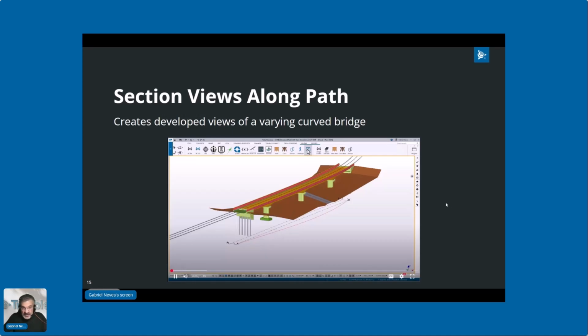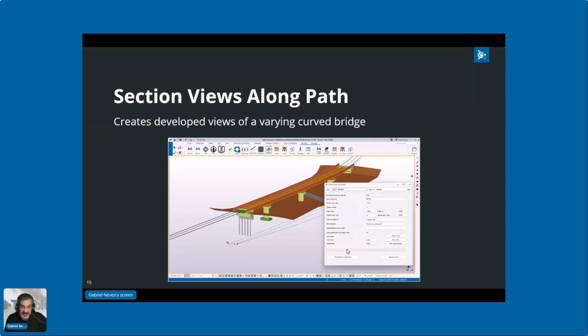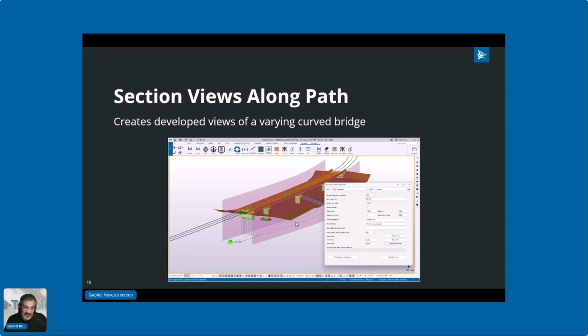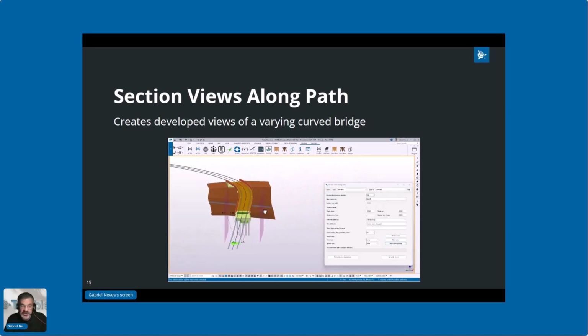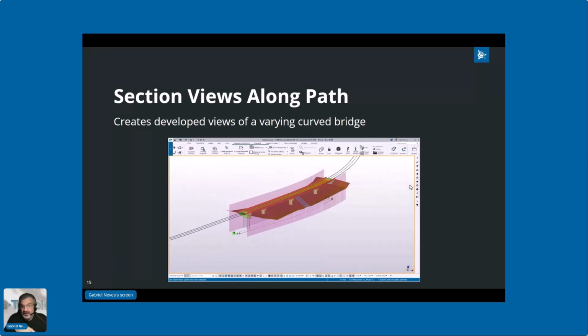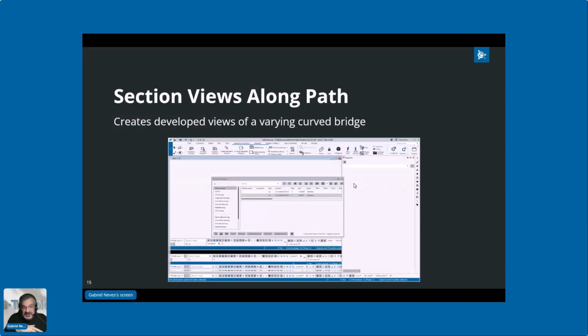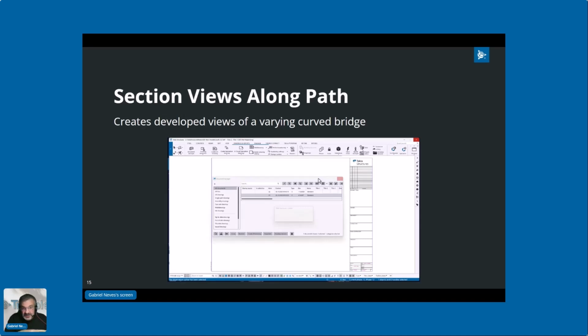So now when we get into the extension, we have already the short line. As I said, we're going to use that. We could pick the 3D, but I'm going to pick the 2D. So now I'm going to look north, and then here just to see the crop view. Eventually I say generate views. So it's a GA with just one plan. And now I'm going to have maybe 80 or something like that views side by side. So here then I don't touch this drawing.